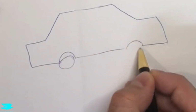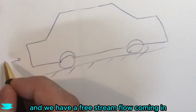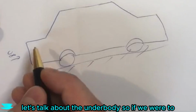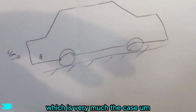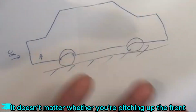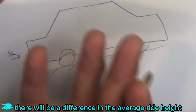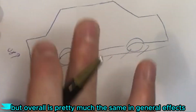So we have the car along the road here, and we have the free stream flow coming in. First of all, let's talk about the underbody. If we were to, let's say, pitch up the front, it doesn't matter whether you're pitching up the front or pitching down the rear, they're approximately the same. There will be a difference in the average ride height, but overall, it's pretty much the same in general effects.